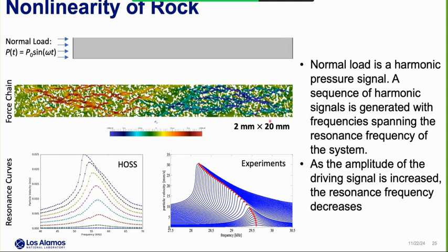micromechanical model for this rock. Basically, we built our model using the micro CT image from part of the rock, and this middle picture shows the pore structure of our mesh, and the white space is the pore space. We also applied a similar boundary condition as the experiment.